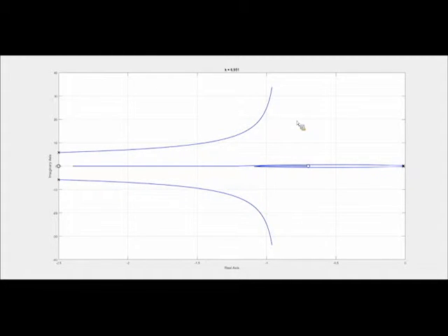That has more to do with what the solutions to polynomials are, because you have a polynomial denominator that determines the poles of the system. If you have an imaginary part for one pole, you have to have its complex conjugate. So if you have a pole on the positive imaginary axis, you have to have its complement on the negative imaginary axis. So it's always going to be symmetric about the real axis.